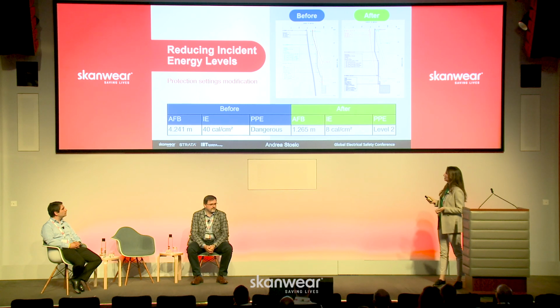Basically, every line will represent a different protective device. And when we started doing the arc flash study for this site, we calculated actually more than 40 calories per centimeter square on this particular switchboard. To be more precise, it was around 61 calories per centimeter square. This equates to over 4.2 meter of arc flash boundary, and the PPE required is rated over 40 calories, which is not that simple.